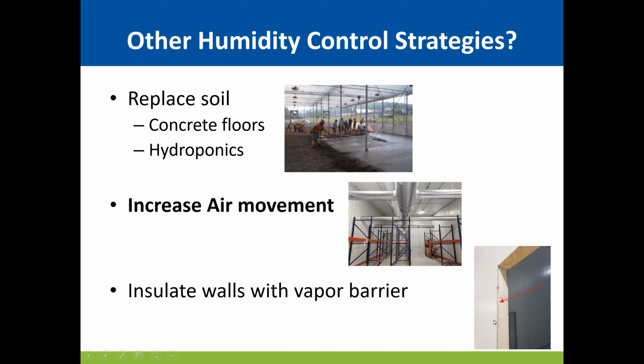Maybe in a humid climate, we want the walls to be a little bit leaky, or permeable, I should say, to water vapor. The problem with that is, one, the outside and inside conditions are changing all the time. So how do you really control the rate of moisture transferring to the other side? And a lot of times those materials are susceptible to mold growth. So we don't want that too.